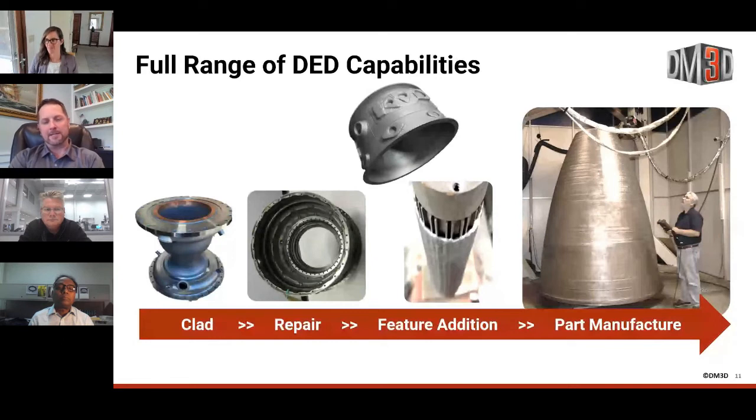And then being able to evaluate how that part fits, and then say, okay, if I do this operation, if I add material right here, well, what's going to happen? Well, this part's going to start to twist and turn, and this flange is going to lift up in this direction. And how is that going to affect my overall? And the first answer would be, can I even repair it successfully? Or is it a losing proposition? At some point, you might find out that no matter what you do, you can't make it work. And at that point, it's better to just not start.